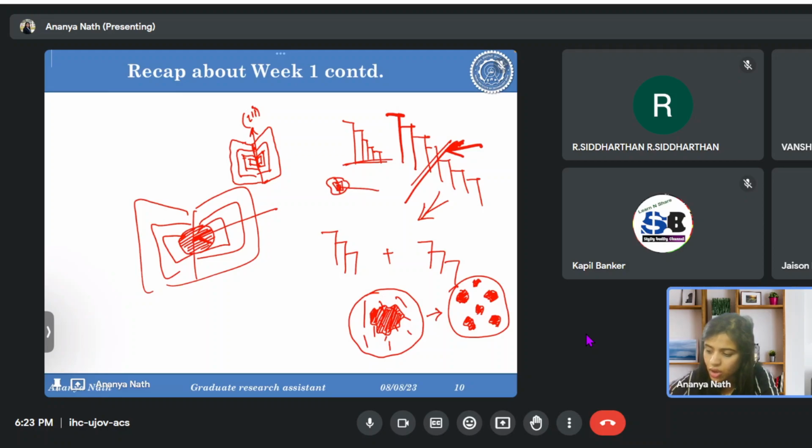If another strontium atom comes and attaches to that, then the other primary silicon present inside the metal will start growing. So this is how we can restrict the silicon growth in a particular way. We cannot stop the silicon growth. Silicon will grow anyhow, but we are just changing the sites so that continuous growth will not occur. And this is what IIT says.